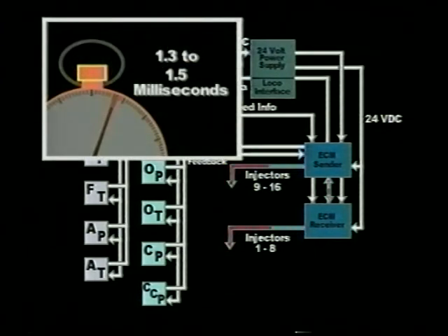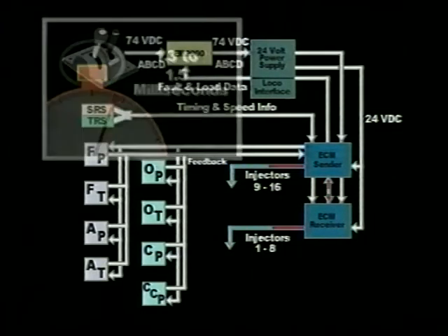Typically, the response time of an injector should be between 1.3 and 1.5 milliseconds. A wide variation in response times between injectors could indicate a problem with the injector or with the wiring harness.